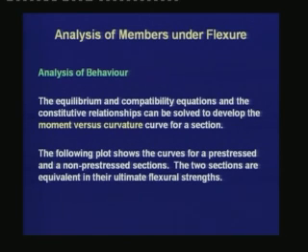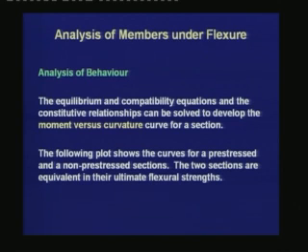In this lecture, we are not going into the details of evaluating the moment versus curvature curve, but we are just learning the basic idea of how to develop the moment versus curvature curve. That means we have a set of equations which are written based on the principles of mechanics. Then we solve those equations iteratively with an increasing amount of a certain variable, say the maximum compressive strain in concrete. Now, once we solve the set of equations for each value of epsilon c, we get the complete moment versus deformation curve. The following plot shows the curves for a prestressed and a non-prestressed section.